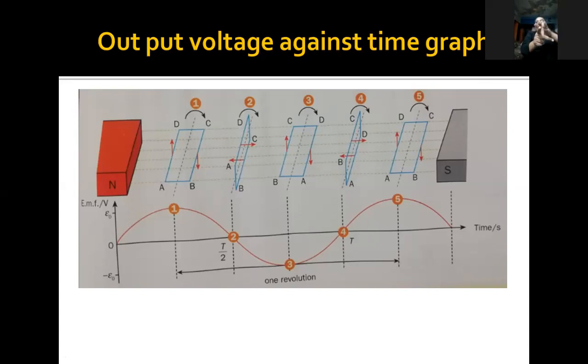The magnetic field is going from north to south, so I will have to twist my arm. The thumb is pointing upward because the BC is going upward. The magnetic field is going from north to south. The second finger is the current. It is showing that the current will flow from B to C. So here, the current in the BC will flow from B to C.